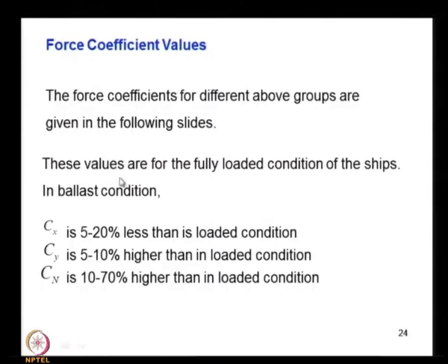When it comes to the other port, during the course of its journey, it has consumed the stores, maybe again 80 to 90% consumed. So, again the displacement changes, resistance changes, underwater portion different, above water portion different. So, that is why these are considered separately. That is what it says, that these coefficient values are usually taken for the fully loaded condition. If it is in a ballast condition, these coefficients Cx, Cy and Cn need some adjustments.